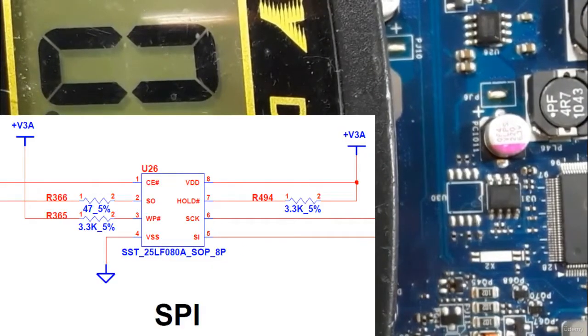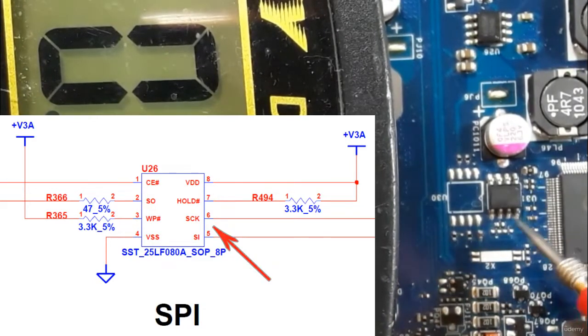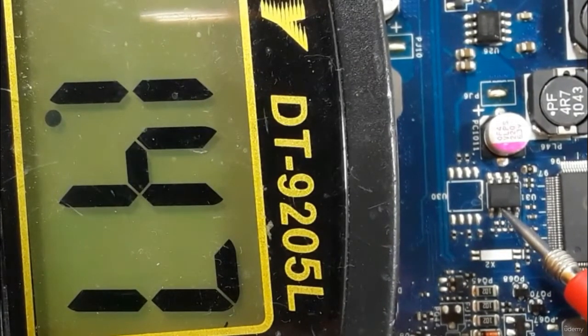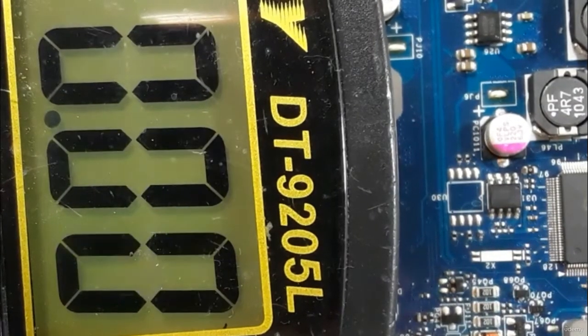So let's check the clock. So the clock exists in pin number 6. So we have here 1, 2, 3, 4, 5. This is pin number 6. So let's check. Here we have 1.5 volt. Okay, so the clock is okay.